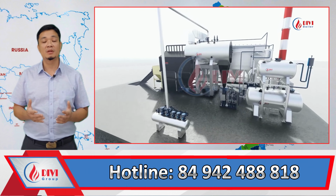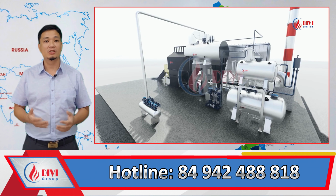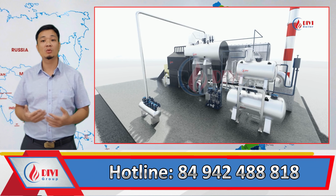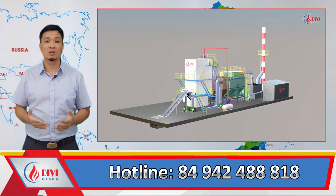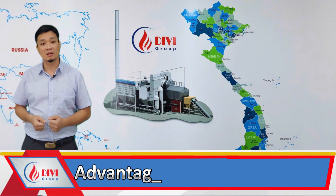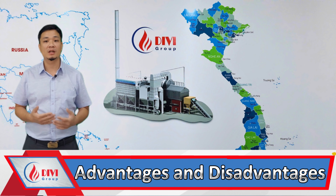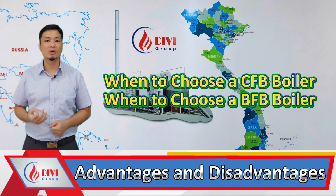For example, the video showing the combination water-fire tube fluidized bed boiler represents a CFB, as it includes a fuel recirculation system. Meanwhile, the video of the 2-drum water tube fluidized bed boiler is a BFB, since it does not include such a system. So what are the advantages and disadvantages of each design? And under what circumstances should you choose one over the other?